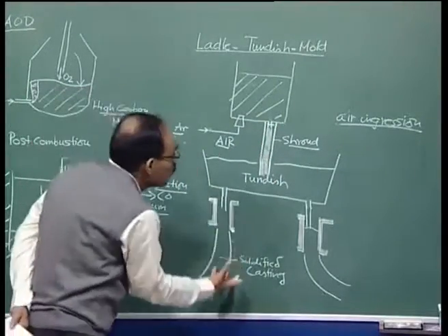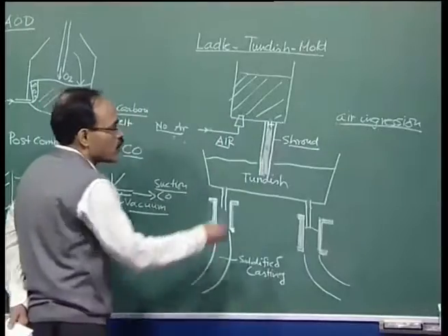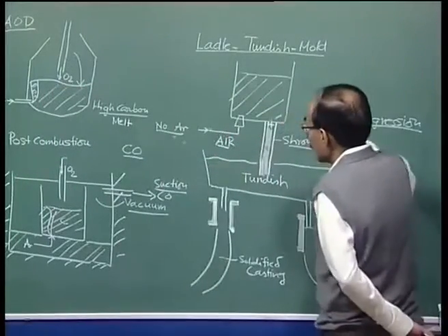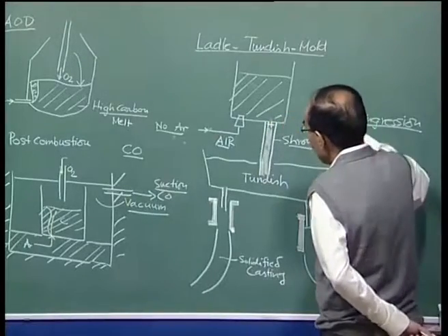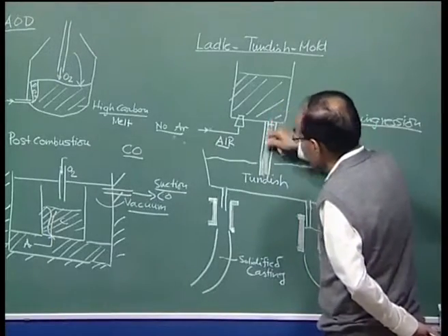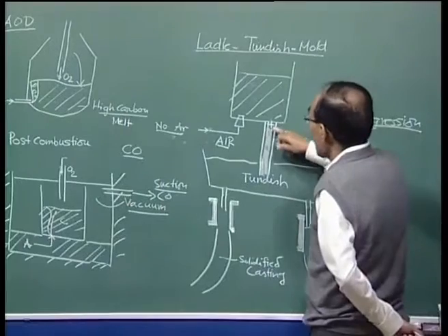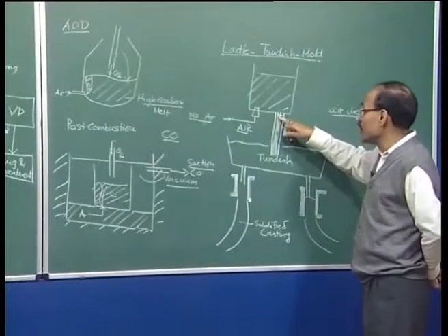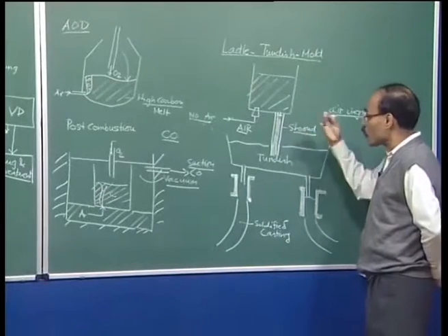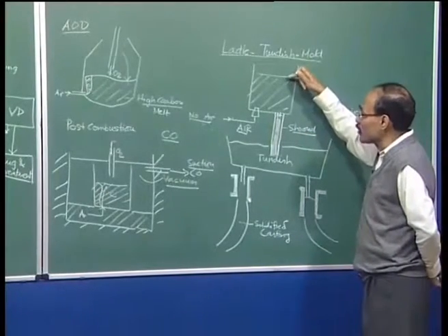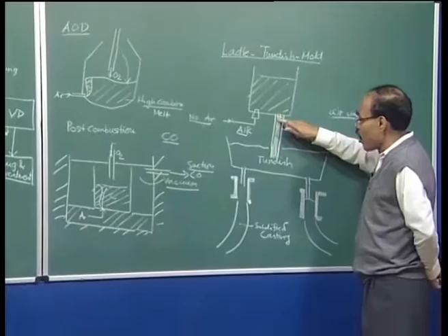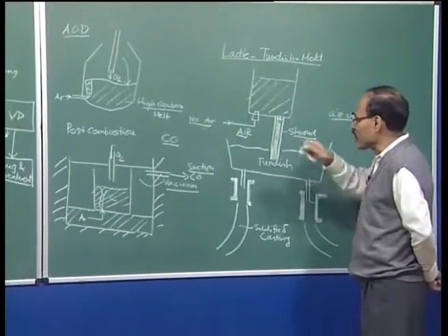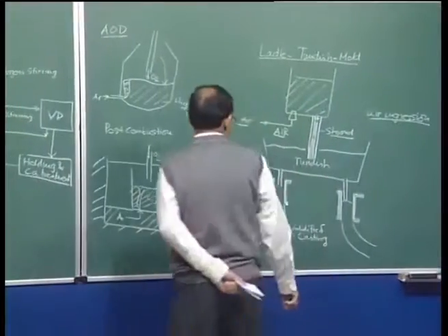So, this tube which is attached to the bottom of the ladle, through the slide gates it can be moved this way, and the openings may be made bigger or smaller, and thereby the flow rate can be controlled. And the flow rate is typically not controlled in the industry manually. It is basically done through a control algorithm which takes into account the melt depth and the diameter, how much it is to be opened in order to pump molten metal into the tundish at a constant rate.